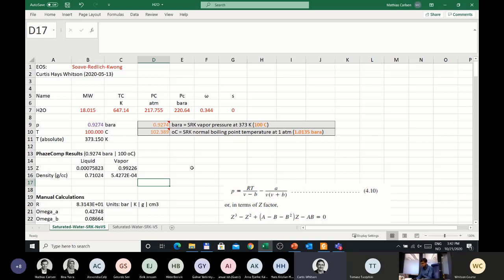The steam density will be very close, but it can't give you the compressibility by better than a factor of 2 or worse than a factor of 2. That's something that nobody really talks about, but it's just a fundamental failure of the cubic equation of state. It doesn't have the correct pressure volume temperature relationship everywhere.